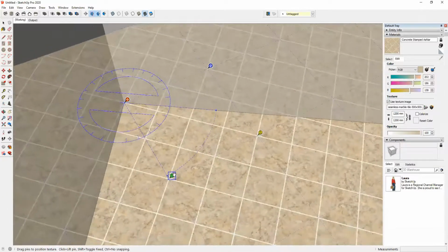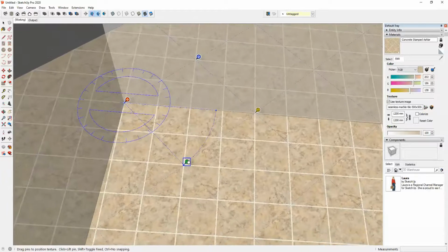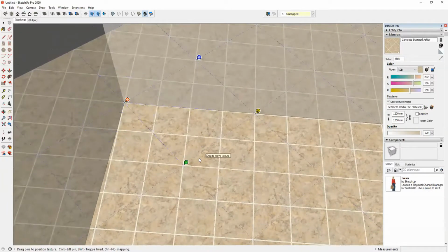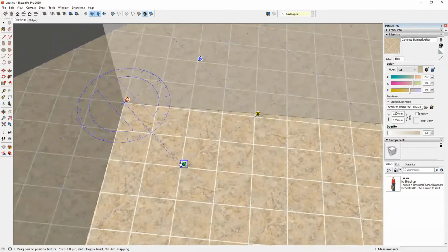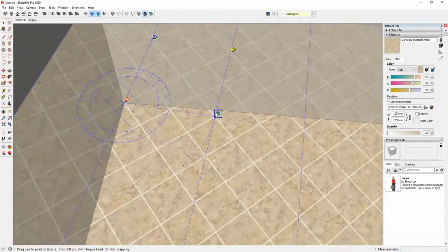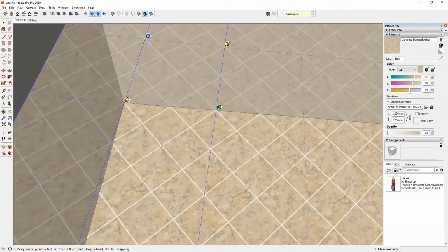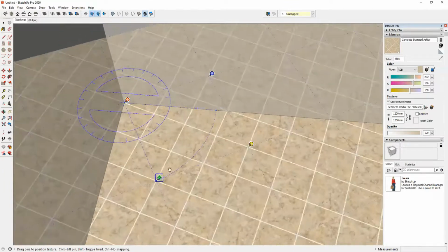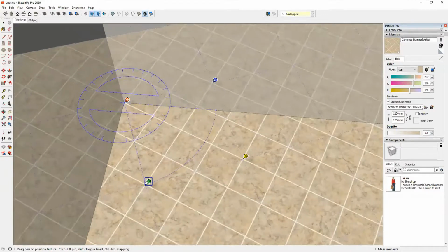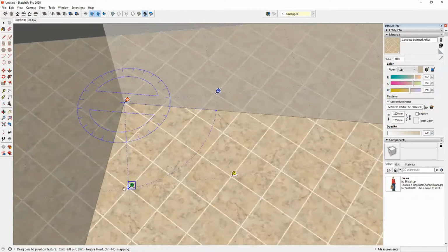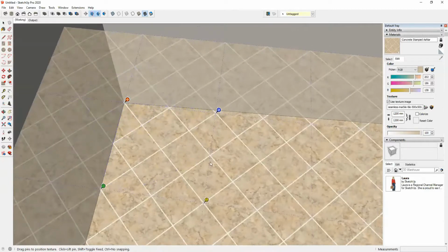Now if you want to rotate it at a particular angle, I don't think we have that option, but you can rotate it. It's better to resize and reorient the image in your external image editor and then apply it here for more accuracy, because in SketchUp we can reorient, but we cannot scale it accurately unless the image, that is the JPG, is created in scale.